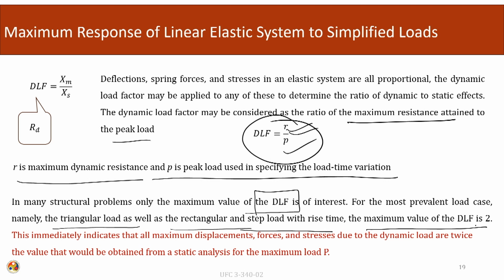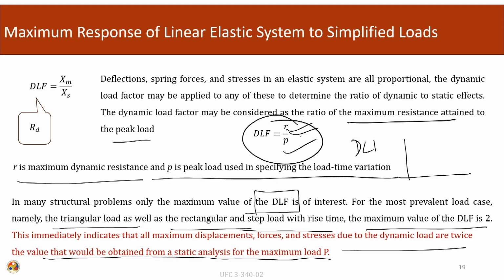This immediately indicates that all maximum displacements, forces and stresses due to the dynamic loading are twice the value that would be obtained from a static analysis for the maximum load P. It means that the maximum dynamic increase in the response is 2.